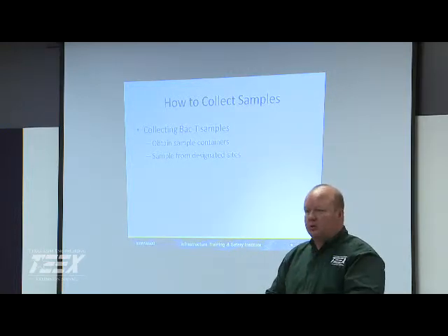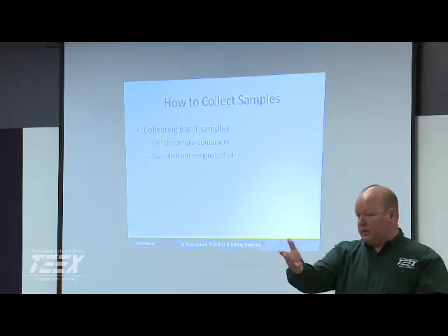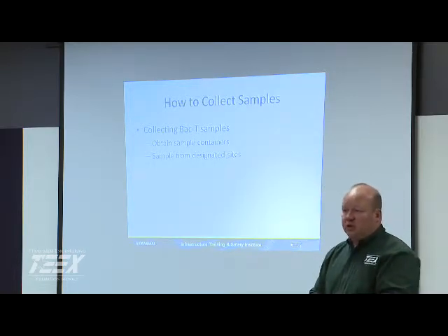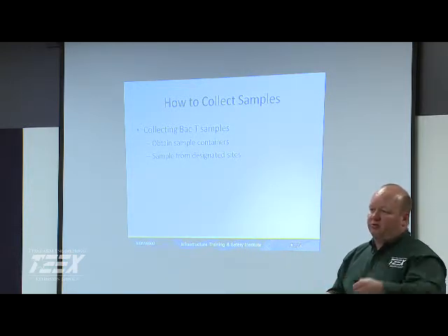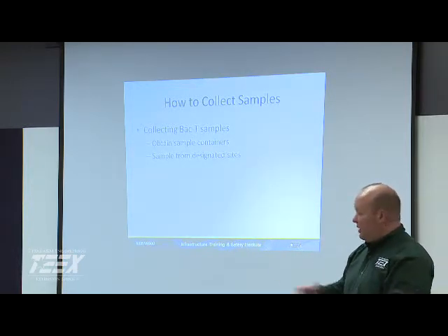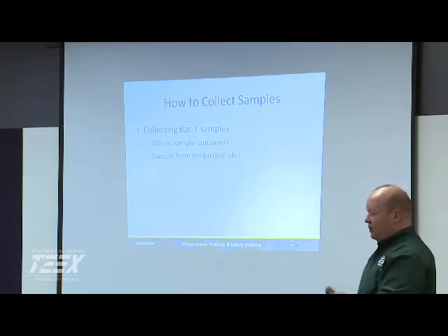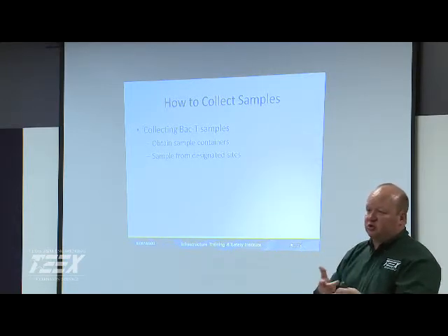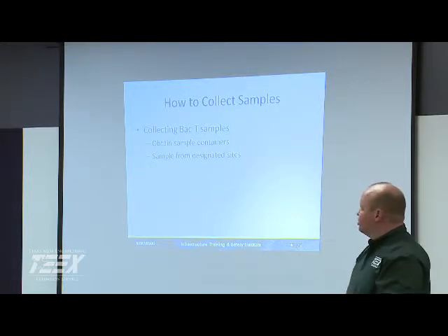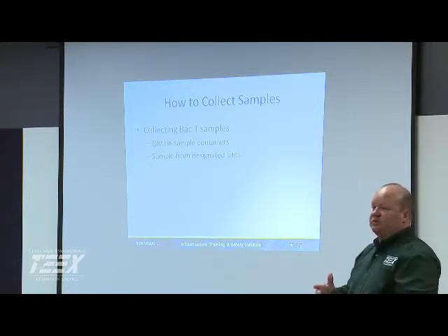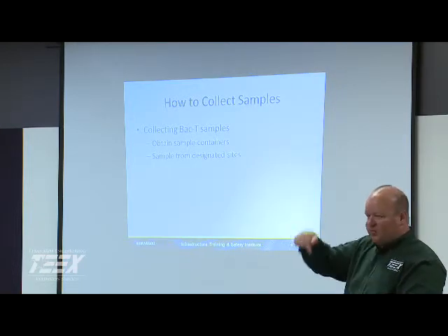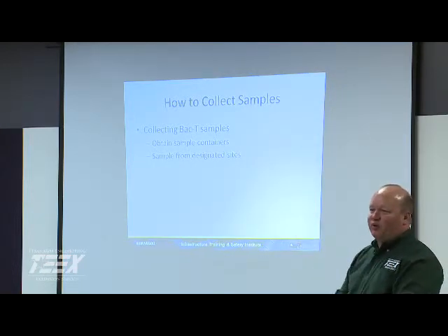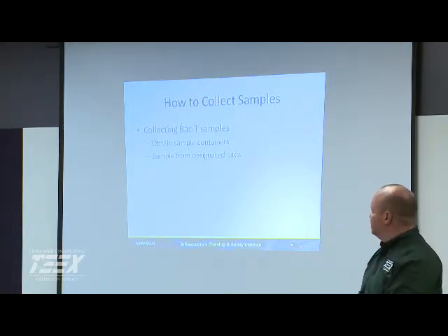Usually they try to wait till the water stabilizes in temperature and things like that. So you're waiting for a temperature change. If you're pulling from homes, normally about 5 minutes, depending on how far your main is, how far it's set back, and how much usage is in the home. But yes, temperature change is a big thing, making sure you have a good residual before you pour your sample. Knowing how to disinfect properly, and knowing what size stream you want. Pencil size. You don't need a full volume coming out, splashing all over the place.